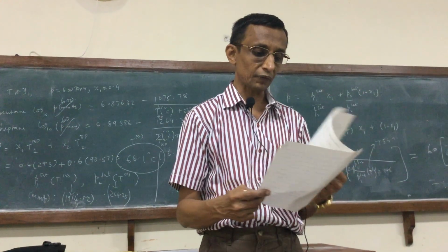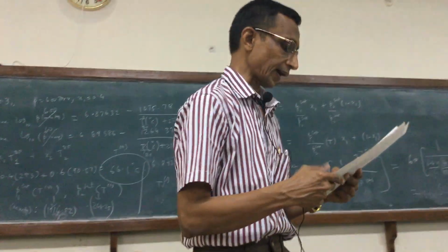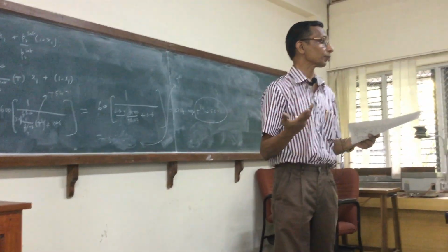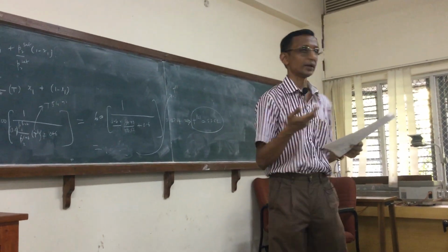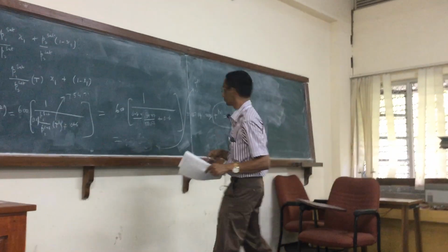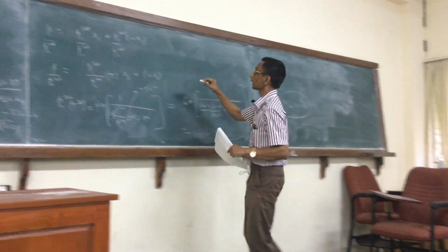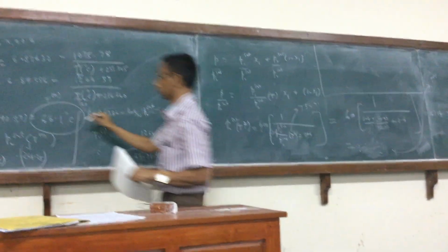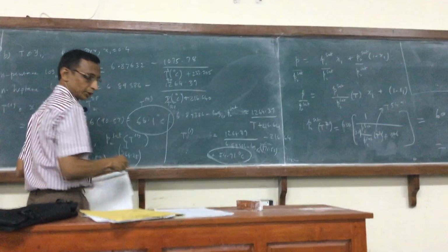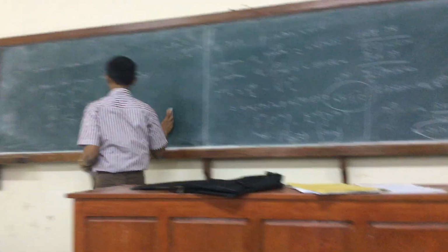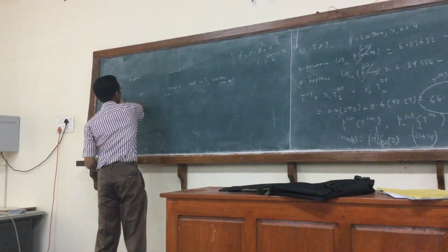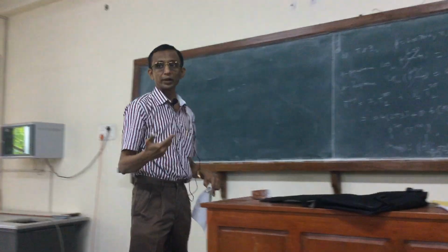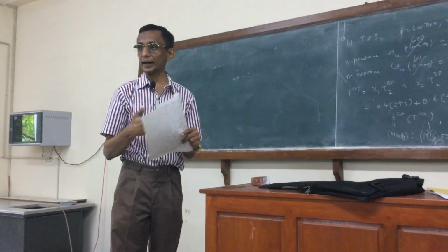But on the other hand, if you look at, for instance, the other algorithm that we use, where we don't impose a mole fraction constraint but simply calculate y1 and y2, let us take that. So I will do that here. We start here again with T0 equal to 66.1. If you recall, that algorithm involved directly calculating y1 and seeing whether the mole fraction constraint is satisfied or not.